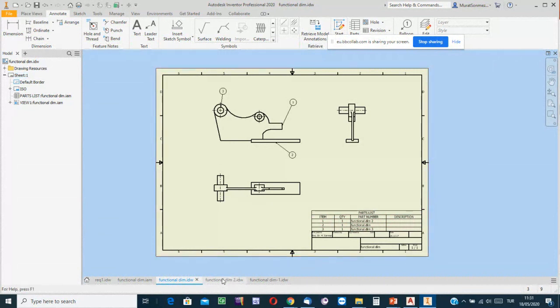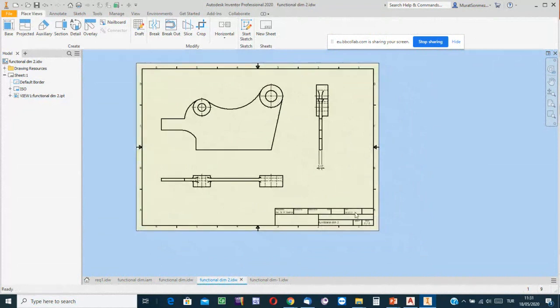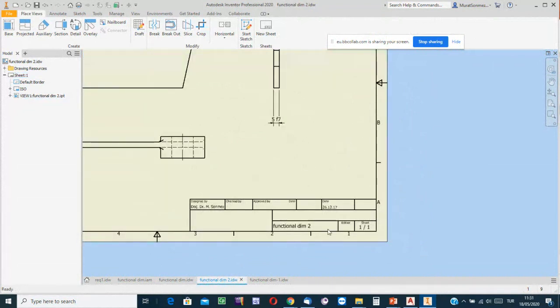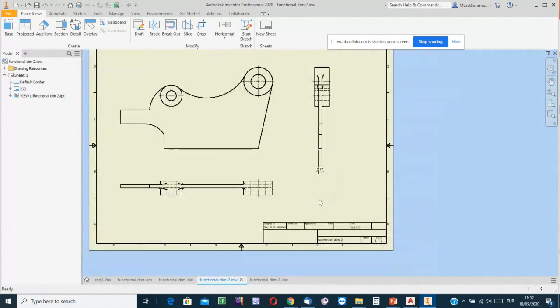And then in this example, let's say the technical drawing, the detailed drawing, is not completed because the quadrant symbol has not been shown. Okay, the name of the company is not written and the dimensions are not shown. So we cannot say that this is a complete detailed drawing, not yet. We have the views only and one of the dimensions. But my purpose is to focus attention on our method, how we can guarantee to have the fitting in the correct order, clearance fit or interference fit, etc. Well,